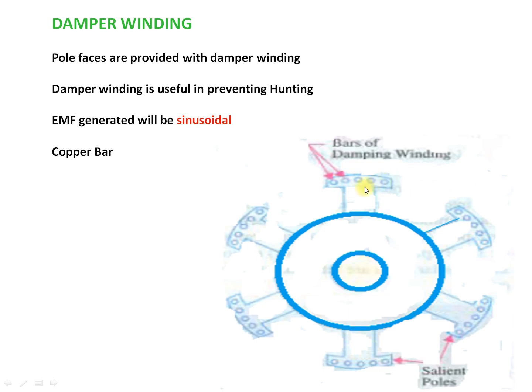So whenever this particular rotor goes out of the synchronous speed, the eddy currents will be formed inside these particular copper bars, so that the rotor will go closer to the synchronous speed, so that the speed of the machine can be maintained at the synchronous speed.